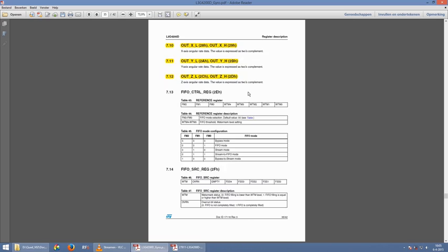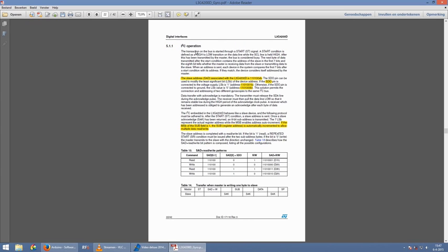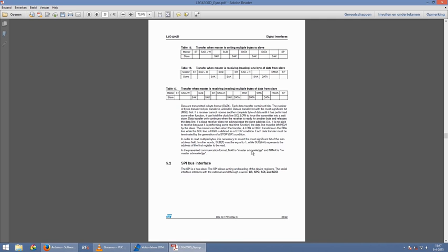The I2C communication protocol that we will use for communication with the gyro is described in the manual. The most important parts are the I2C address of the gyro and the fact that you can change it via the SDO pin. Depending on the state of the SDO pin, the address of the L3G4200 is 104 or 105 in decimal notation. On the breakout board from Parallax, a pull-up resistor is connected to the SDO pin, making it the address 105. All the other interesting parts for communicating with the gyro are handled by the wire library that we will use. The wire library comes standard with the Arduino software, so you don't have to download it.